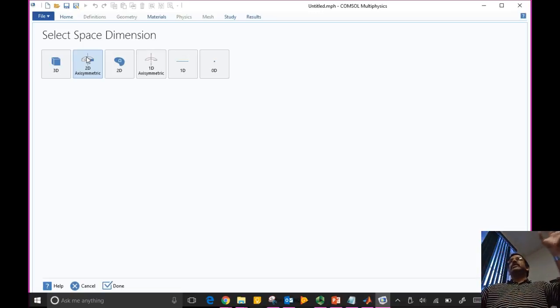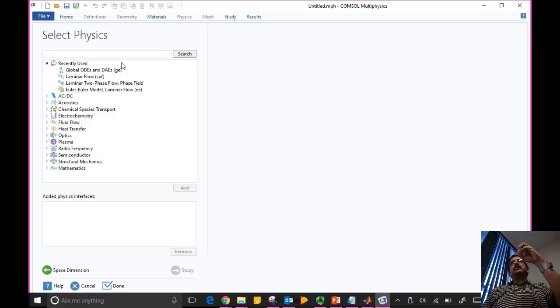And there are reasons why we will come across axisymmetric models when we look at fluid mechanics models. And then you have 2D. 2D axisymmetric means in any plane, variations are there in 2 dimensions, but in the 3rd rotational dimension, there is no change. So the problem effectively is a 2-dimensional problem. And you can have a 2-dimensional planar problem.